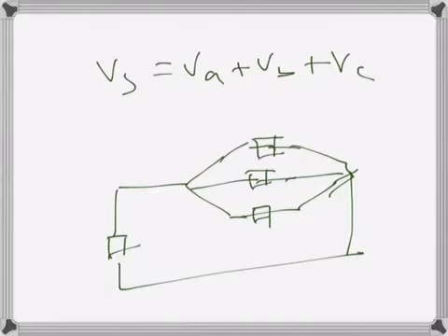So what it says is, at any node, wherever more than 2 branches meet, or 2 or 3, whatever, we can see that here current is split into 3 branches. So this is, let's say A, this is B. So at any node where more than 2 branches meet, the sum of entering current will be equal to the sum of leaving currents.